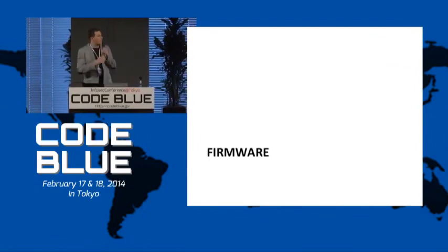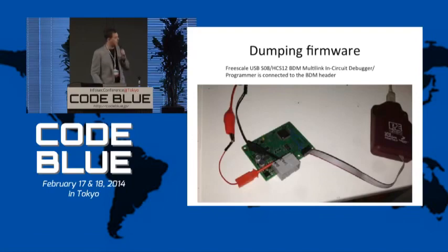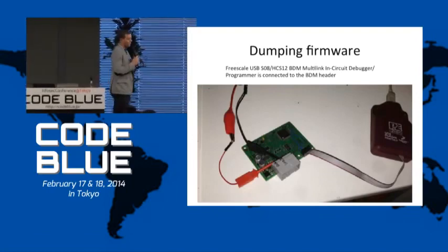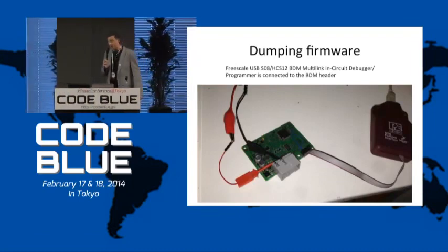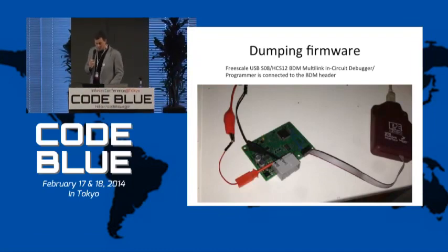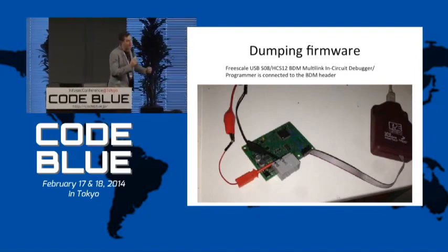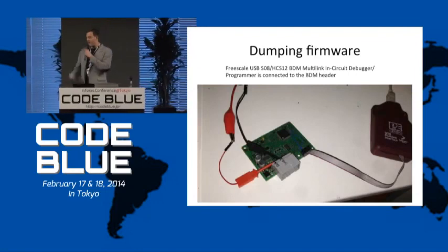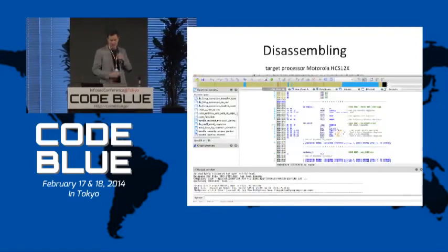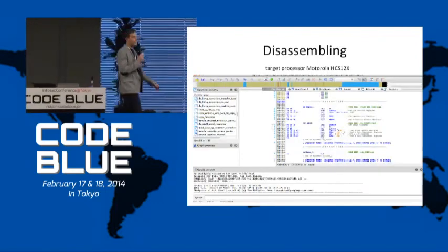Well, maybe you're even worried about people stealing your code. We got code off of a few of our ECUs just by identifying debug test points, buying a hardware debugger, and then dumping out the code. This wasn't over CAN, but we took them out and dumped the code out, and Charlie and I are reverse engineers by trade. This, again, was the easy part for us.